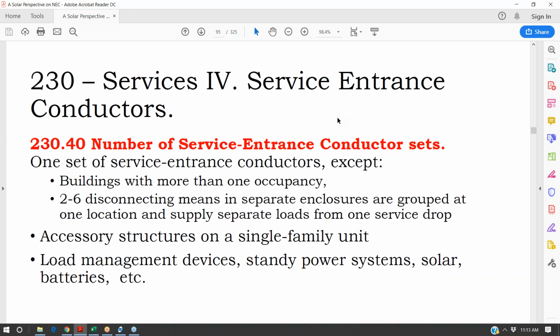And that usually allows you to feed an auxiliary garage or some exterior power outlets, and you don't have a main breaker on that combo panel. The panel will just go into the inside with a couple of breaker slots on the outside. Once you get more than six breakers on that panel, you need to have a main.